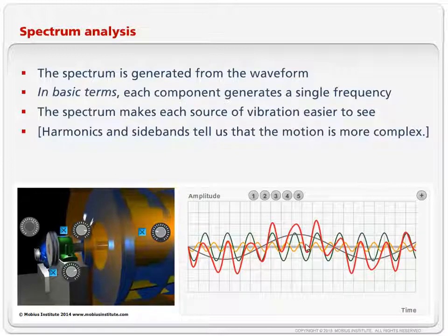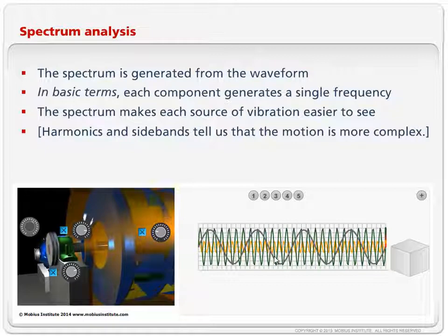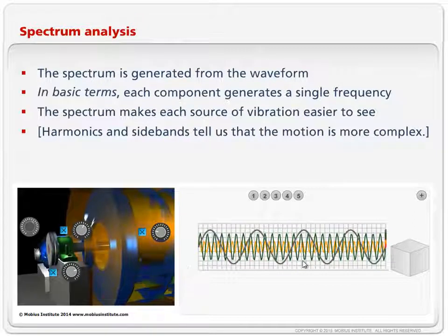That's there, but as you can see, could you look at that red waveform and see whether it's balanced or there's a bearing problem? No, it's difficult. So that's why we use spectrum analysis. Spectrum analysis, so there's those three signals again with the red one turned off. There's the three, and I can turn down the bearing and, whatever.